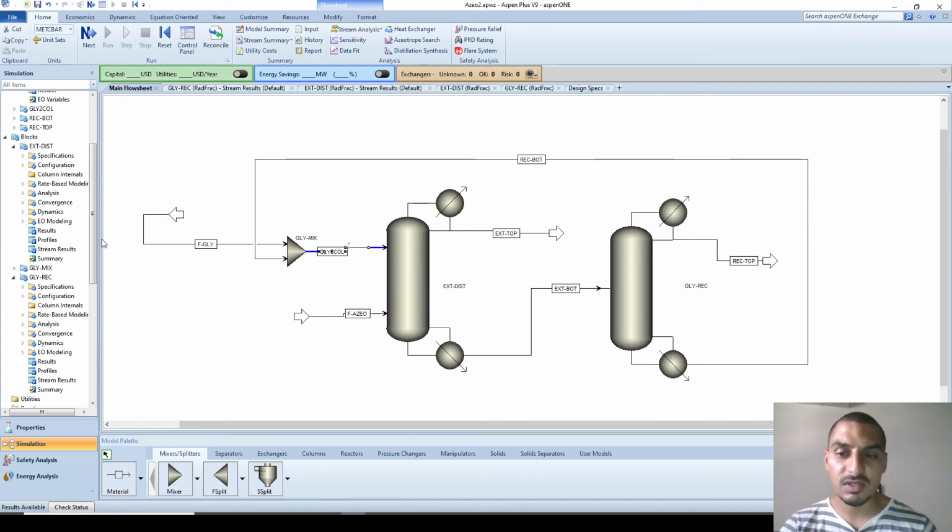It's not, this stream is 128.8. This is the stream that must be 128.8, so that the flow sheet goes as I was planning before the recycle. And these are the values that I got before the recycle stream. And this stream is just going to be a makeup stream, to compensate any losses in the glycerol either here or here in these two streams. So if I lose any glycerol here, this is going to be compensated by the makeup stream here. So this should be a small amount of glycerol.